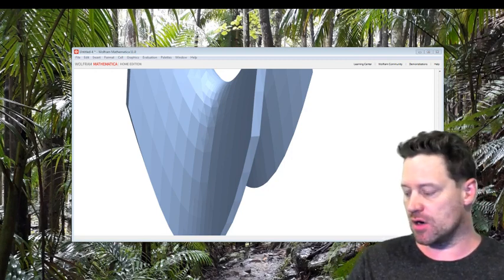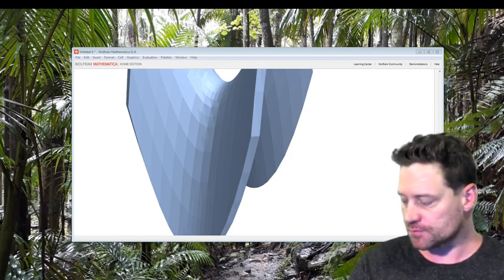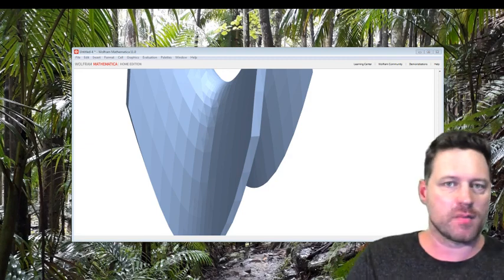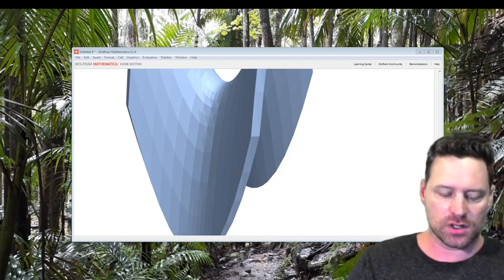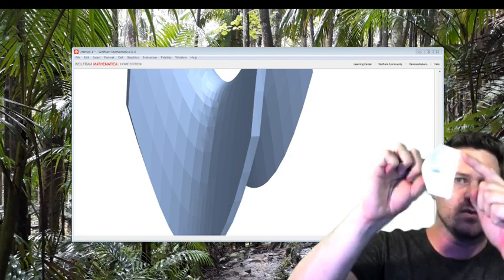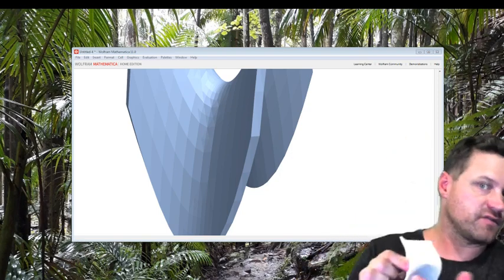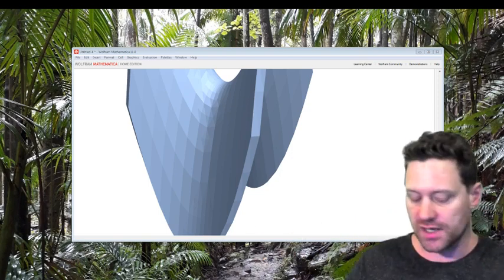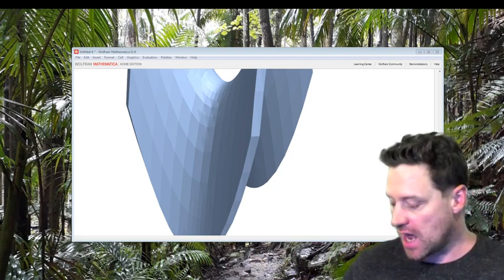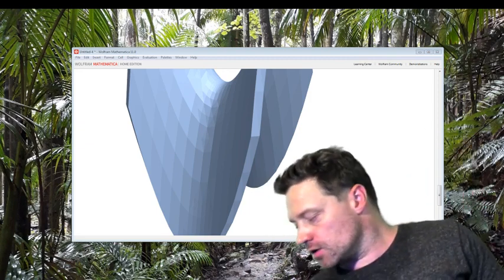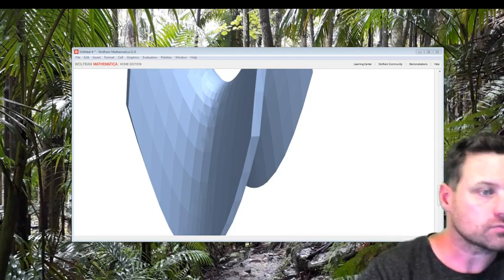Because when you have to go and pull this support material off, it can be a bit of a messy process. So you want to avoid it. I don't think you can see it, but here is a place where I had to use supports, and it's fairly rough. All right, so you want to avoid using supports when you can.